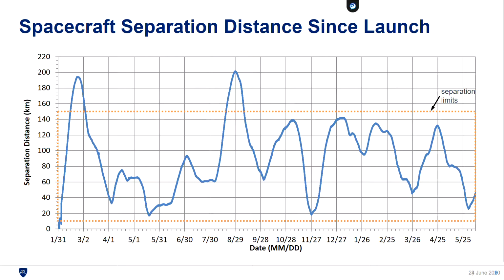In August of 2019, we had a series of safe modes and command lockouts on both spacecraft, and they exceeded the desired separation before we were able to get enough drag commands in and recover the spacecraft. So it was after this experience that we began regularly adding those manual commands midweek and being more aggressive. Then in November, another series of safe modes and lockouts led to the spacecraft coming within 20 kilometers of each other before we were able to turn the separation rate around.